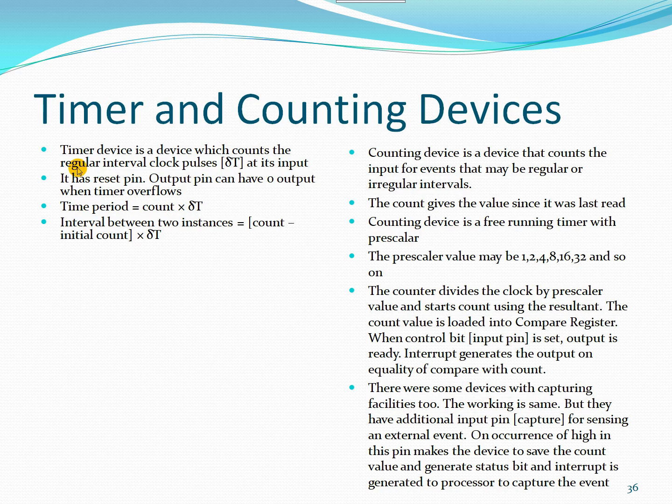Upon reception of either the rising pulse or the trailing pulse, we will be having those pulses as an input, and we will be counting those values up to one preset value. The maximum preset value will be given to the timer. Based upon the value of the preset, the timer will be upcounting.